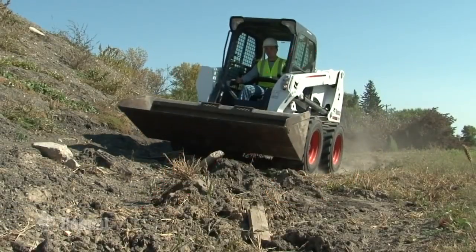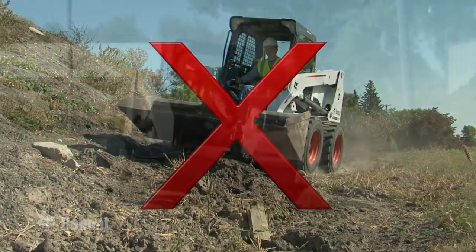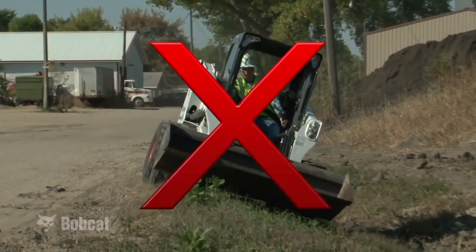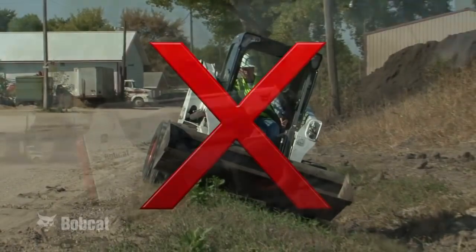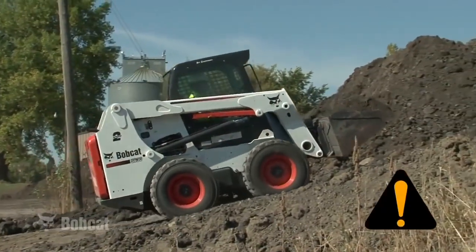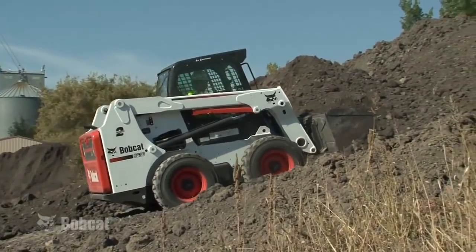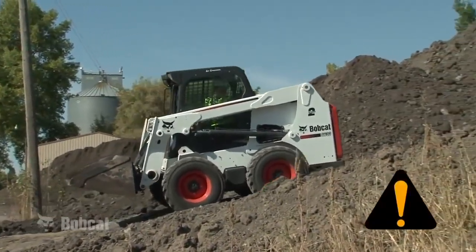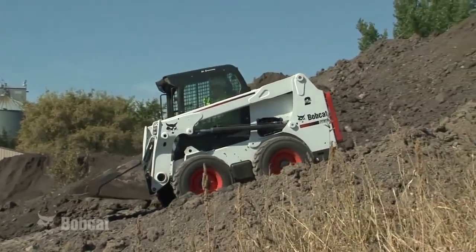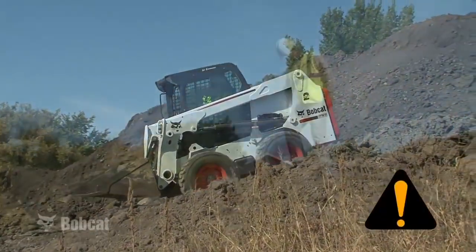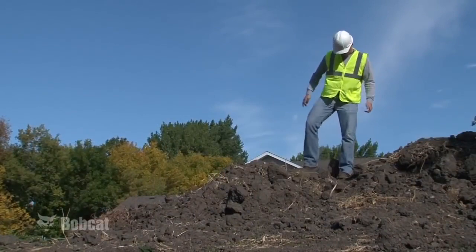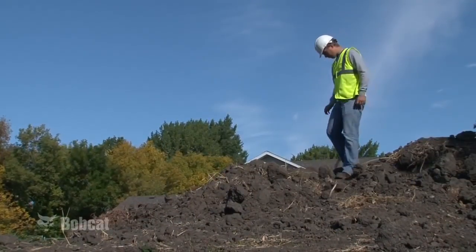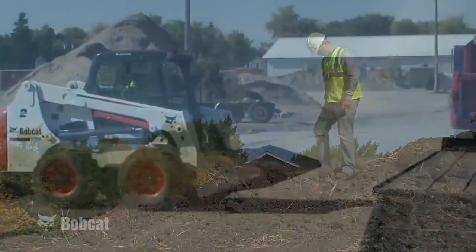Avoid rough terrain if possible. Be careful on slopes and avoid traveling across steep slopes. Drive straight up or down slopes and keep the heavy end of the loader uphill. With no load, the rear is heavier. Refer to the operation and maintenance manual for specific instructions for your loader. Always check the surface conditions for adequate traction to avoid sliding down a slippery slope, causing a rollover.